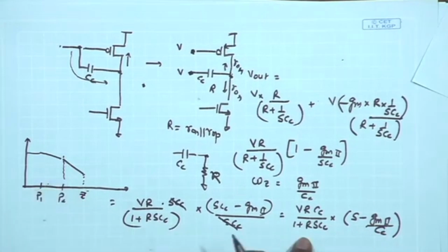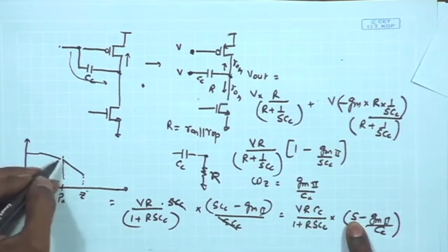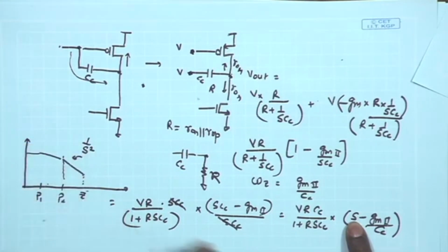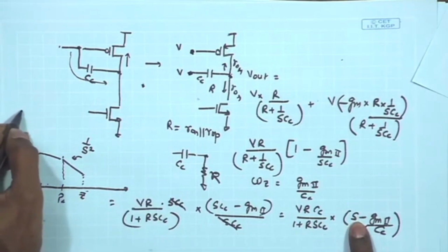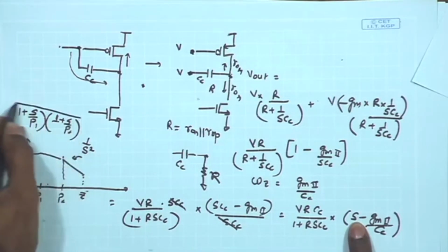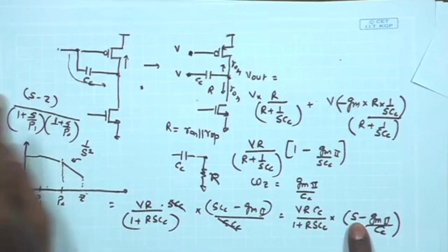And after this, once you cross this 0, this omega term becomes dominant, you can ignore the second term. As a result, this is going to cancel out with the other two terms that you get till this point. So, till this point the expression of the overall gain was dependent upon omega square, but after the 0 you get another omega in the numerator, right, because of the two poles. Remember, you have 1 plus S upon P1, 1 plus S upon P2 in the denominator, and then now you are having the S minus Z term coming over here.